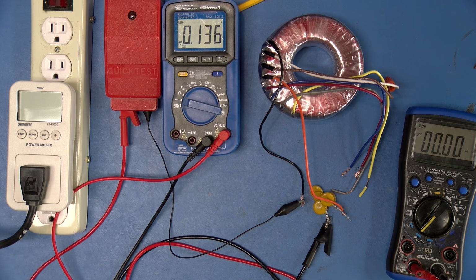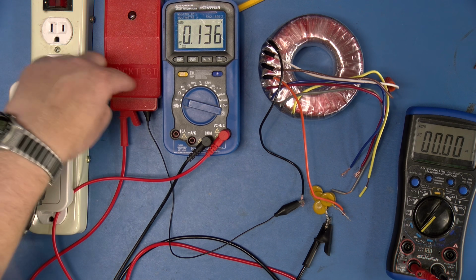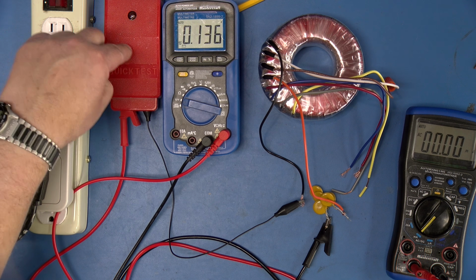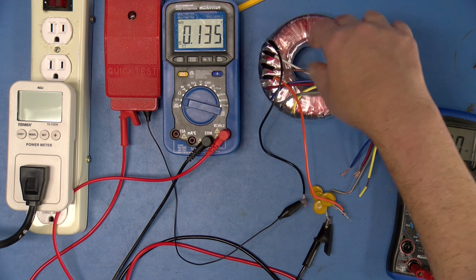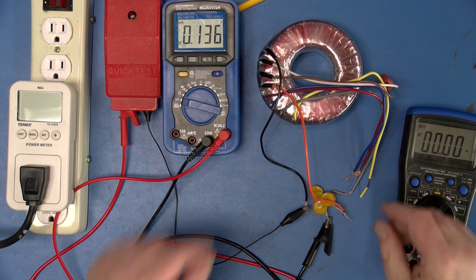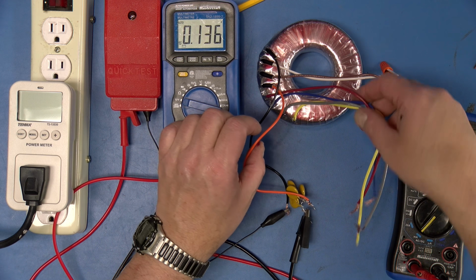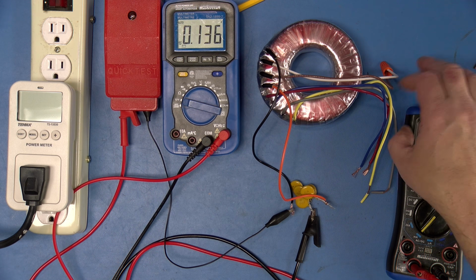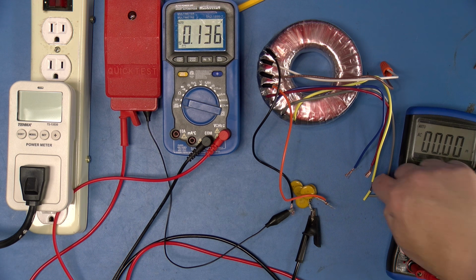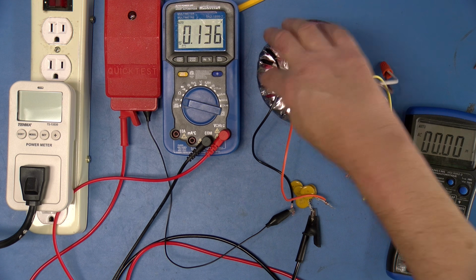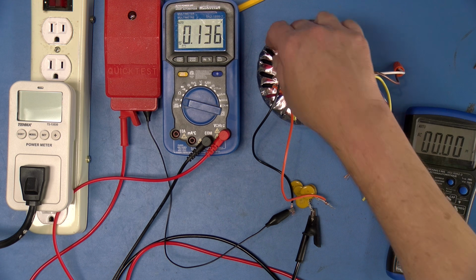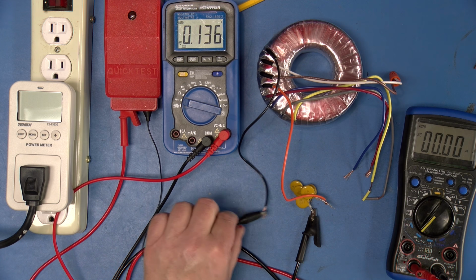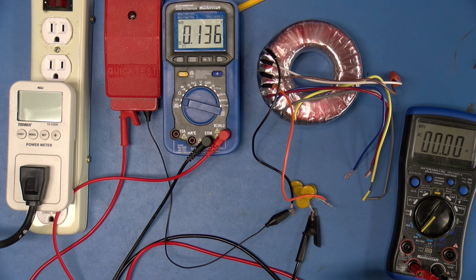And here's the demo. So I have an AC voltage supply here, attached to this quick test, and the line voltage goes into here. Here is going to be our inductor. It's a transformer core. It has some secondary windings that are just sitting here, not attached to anything. It has a pair of primary windings. I've put them in series. If it was a transformer, it would be a 240 volt transformer that way. And by the way, these are the same cores that I used in the electromagnetic chains video.